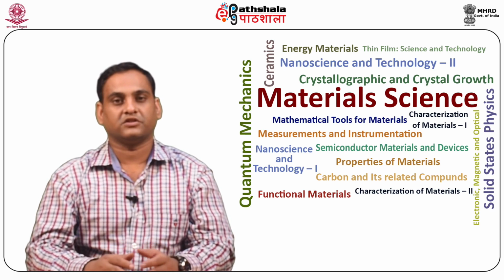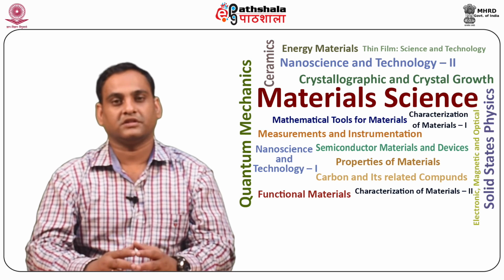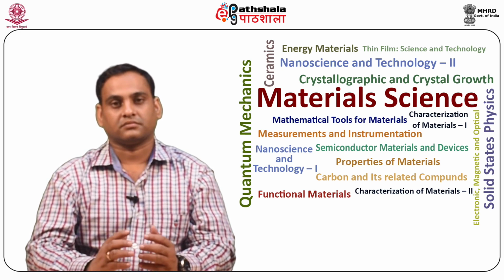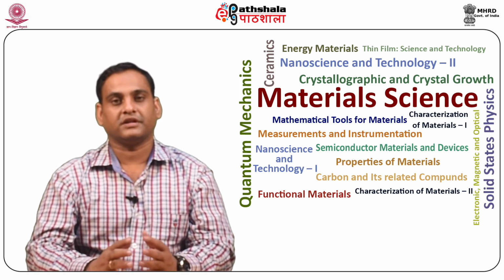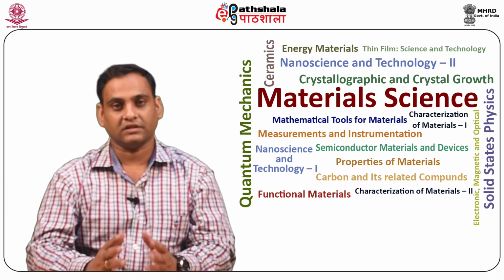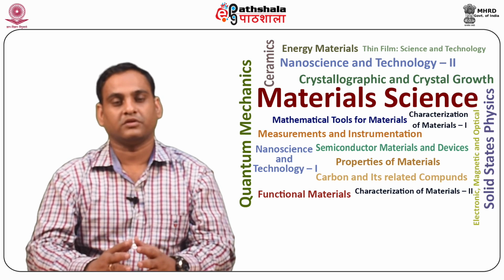There are special grades of nickel iron alloys that have zero magnetostriction and zero magnetic anisotropy, such as mu metal, which is produced by a careful heat treatment and minor additions of copper and chromium. These alloys have extremely high permeability, up to 3 lakh, and intrinsic coercivity as low as 0.4 ampere per meter.